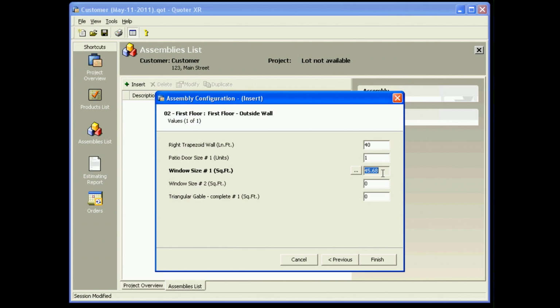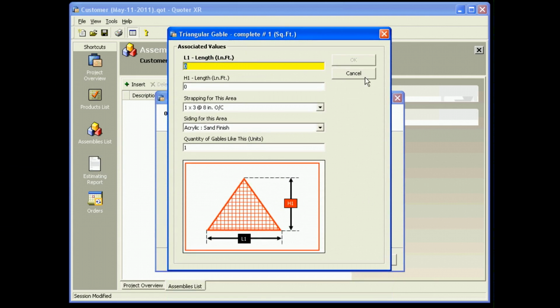So if you have selected casings on the inside or some kind of siding on the outside, it's going to generate all the proper trims and subtract all the siding that doesn't go in these holes and the insulation and everything you don't need. So you can go like that for all your window sizes. And well, here we got gable, which you could also fill just like we did in the other video.